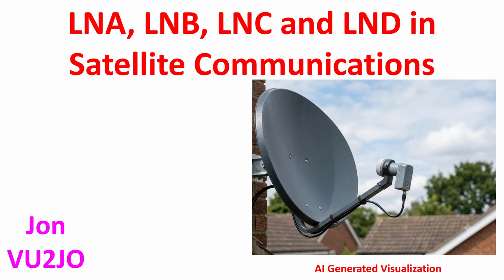In satellite communications, the terms LNA, LNB, LNC and LND represent different configurations of the front-end RF hardware mounted directly at the focal point of a satellite dish antenna. Their primary jobs are to amplify the incredibly weak microwave signals descending from space and, in most cases, translate them to lower frequencies that can travel through coaxial cables without massive signal loss.